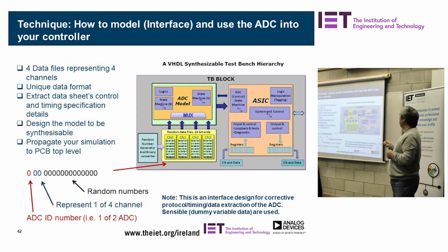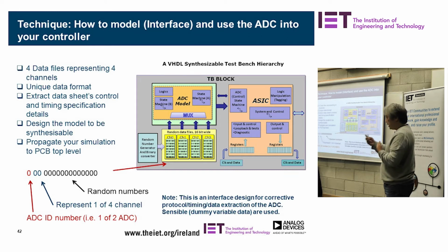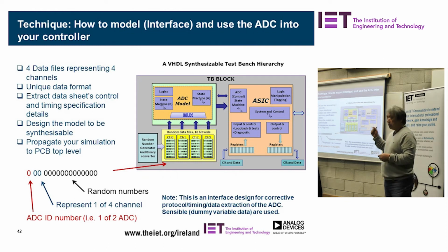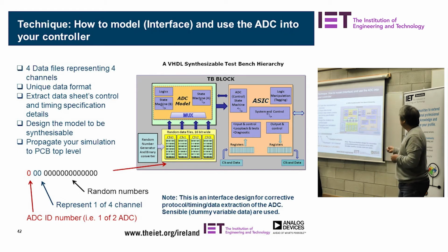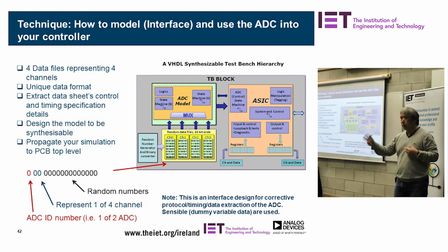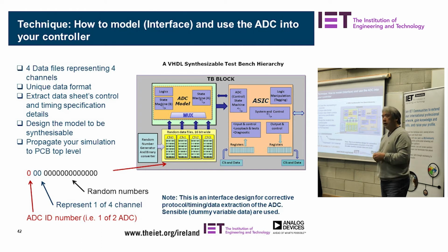So I started designing my ASIC transaction model to get the information back and forth, and I have a loop back as well. The loop back is quite unique because it tests the whole functionality, for later-stage fiber optic applications. So this interface, I managed to model. You can see that by spending some time in the initial stage of your project design, you can do and model quite a lot. And then when the PCB comes back, you can work straight away on debugging it.